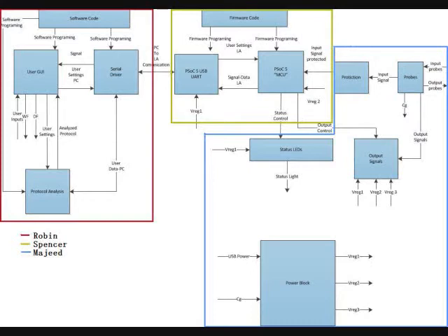The GUI is what the user will see and where they can input settings like how many samples to take. This is also where the waveforms will be displayed. The users will be able to save data waveforms and also be able to open previous data waveforms. The serial driver is the software portion that communicates with the PSoC over USB. The protocol analysis will decode our data protocols, which will be in UART.